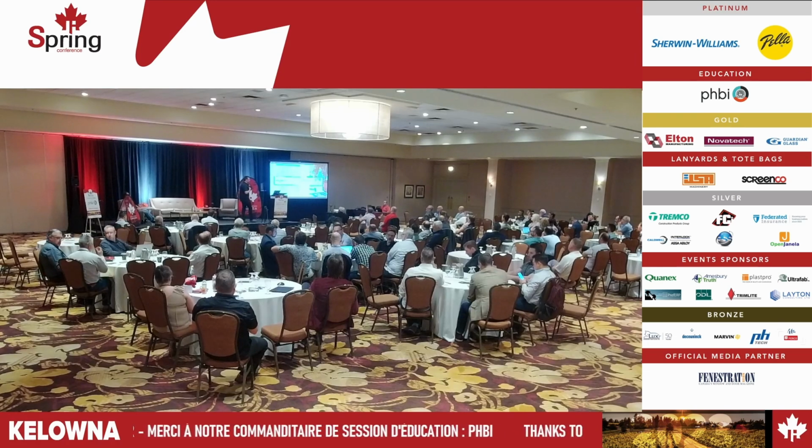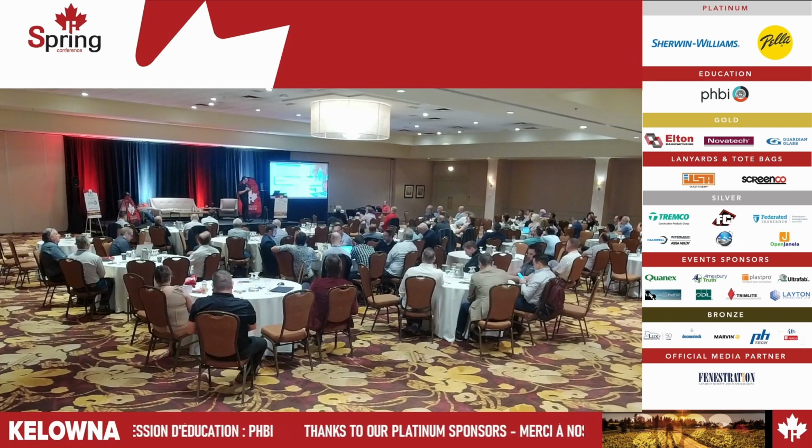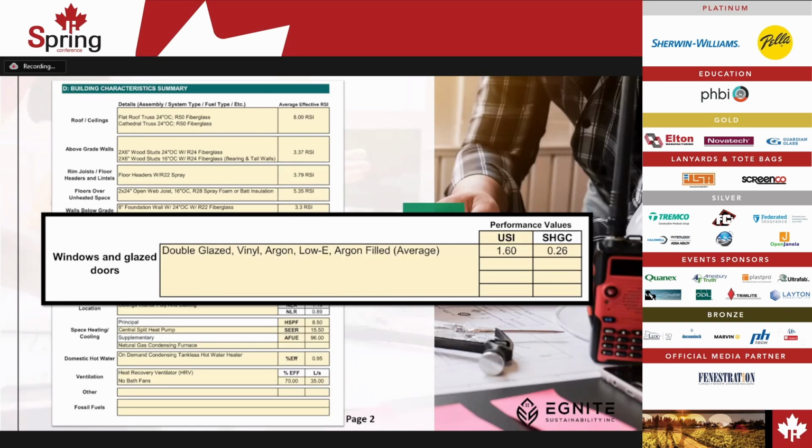For patio doors? We do, yeah. Typically, if it's a simple spec home and we don't need anything too crazy for a window package, we'll just spec an average window performance value of like 1.6 and 0.26 for solar heat gain. As long as the average package is meeting those requirements, it's fine.